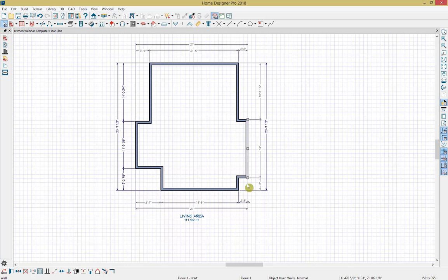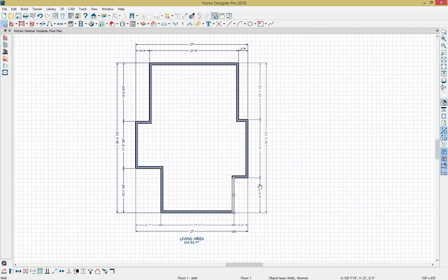And like I said, we are just working our way down this one. As you can see here, I selected the perpendicular dimension to this wall, and let's change this to 3 feet, 4 inches. Then select the parallel wall, and you can change this to 8 feet, 5 inches. So there's two ways that you can dimension. You can dimension with the parallel dimension and the parallel wall, or the perpendicular dimension.